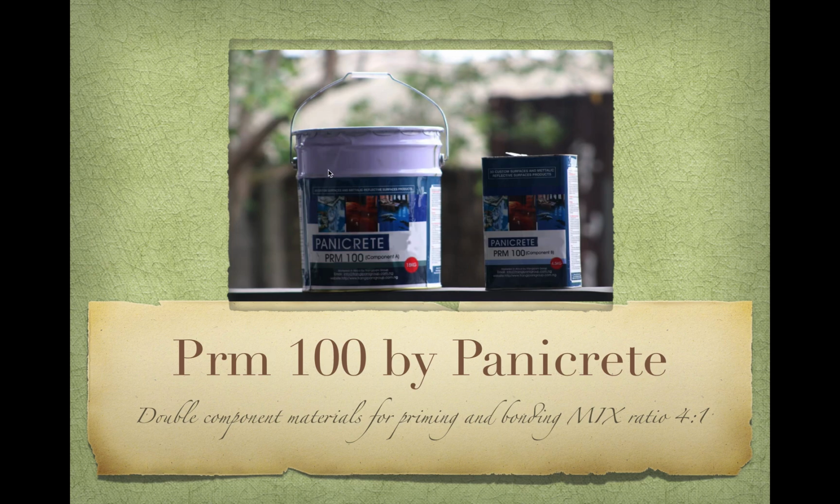The larger component, component A, you need 4 of it to mix with 1 measure of component B. For example, if you are using a 1 liter bucket to measure, it means you are going to take 4 liters of component A. You measure 4 of the component A to use with 1 of the component B of the PRM100. You mix them together, then you apply them.